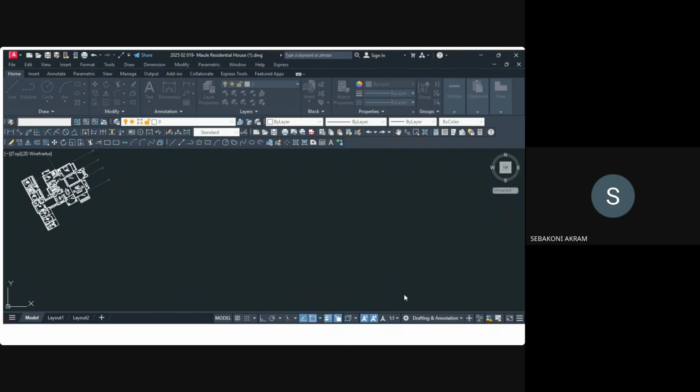Okay, let me repeat the process. After you type the command layer delete, it gives you two options: select object on the layer to delete, or the name of the layer. So me, I don't want to select here, because the things that I'm seeing on screen are the two layers that I do want to stay.